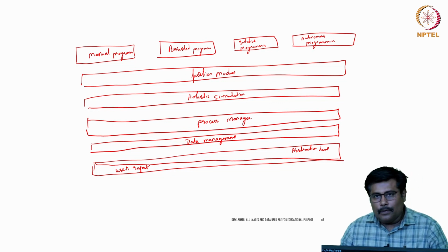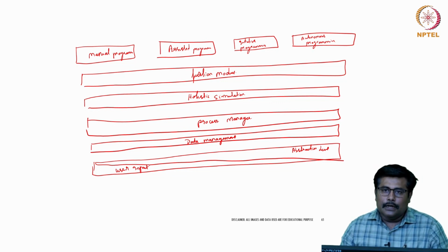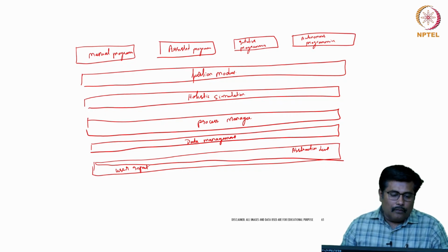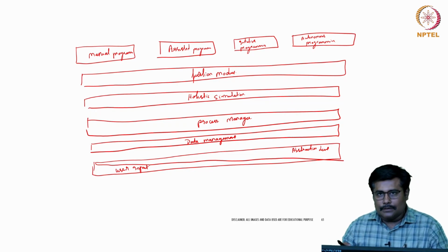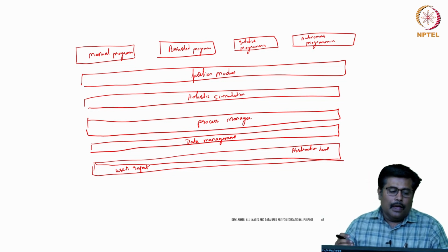Now, when we discuss the holistic simulation, it is mainly meant to enable offline programming and self-learning operations. A simulation of the whole assembly is necessary, including the robot, robotic peripherals, sensor systems and the components to be assembled. Calibration methods are used to reduce the gap between reality and simulation, ensuring a seamless transfer. This is particularly relevant in microassembly, as even a small deviation can have a major impact on the quality of the assembly.